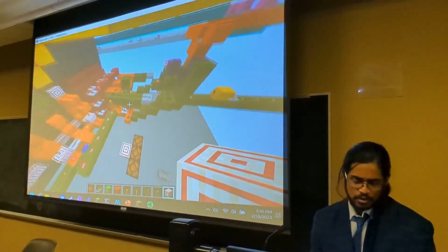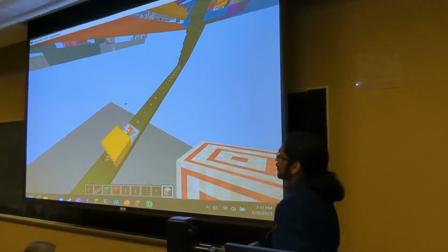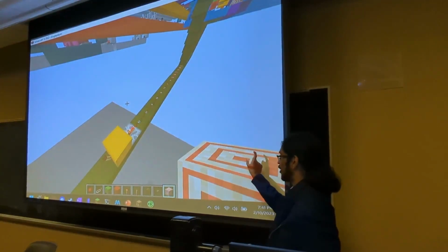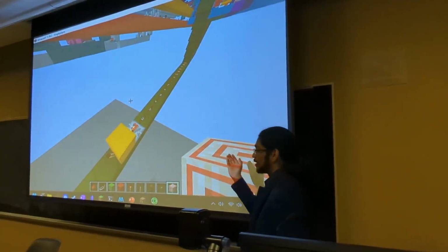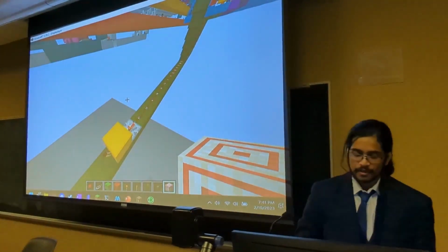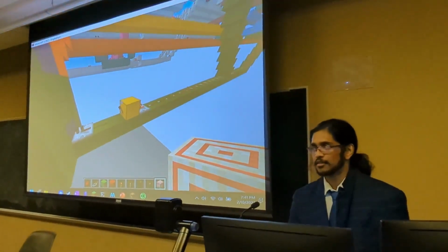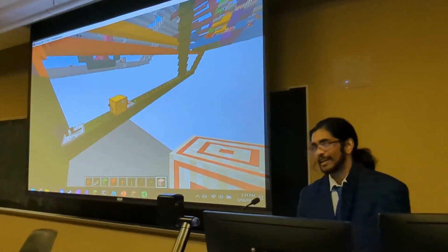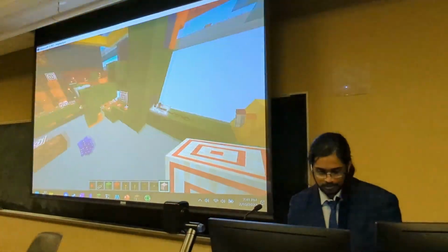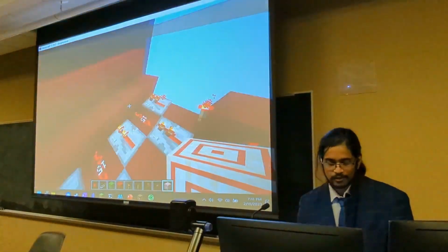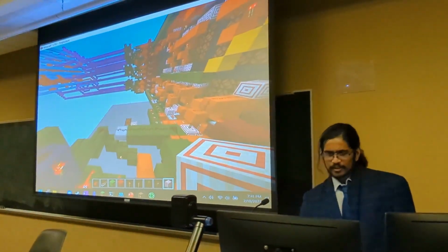And then for displaying who just won, so if X just won, then that means that they created a 3 in a row, and they placed one down to do that, and so now it's O's turn because the turn flip-flop will flip on every valid turn. So if X just played one and we have an O as whose turn it is, then that means that X just won, right? So we just invert the turn signal and give it to the win memory display module over here, right? So that's it.